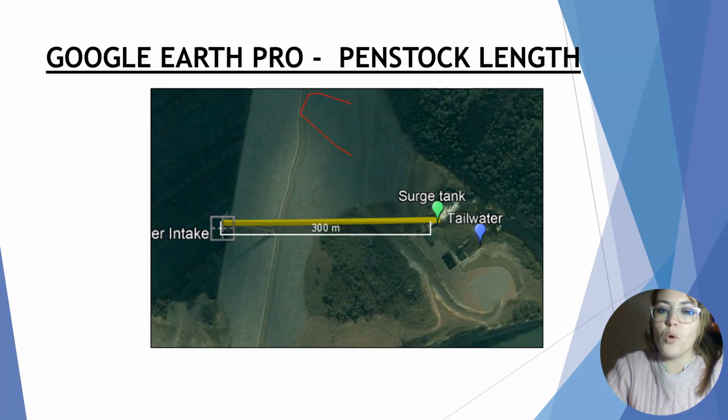For the penstock or conveyance channel length, I had one notable limitation of Google Earth Pro. This was the inability to accurately measure lengths of paths drawn in, due to the line drawn following the natural terrain level. This limitation necessitated an estimation approach for the penstock length. This estimation may produce some uncertainties, so should the project proceed, more field measurements or advanced remote sensing techniques are required to be precise about the underground components.